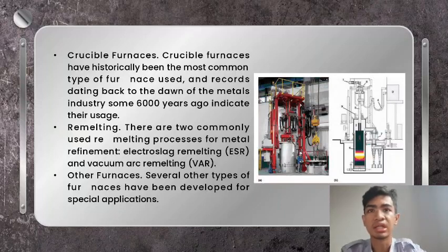This cold melting technique prevents the highly reactive liquid titanium from dissolving the crucible because it is contained in a solid skull frozen against the water-cooled crucible wall. The solidified skull creates a corrosion-resistant protective layer on the containment vessel surface.